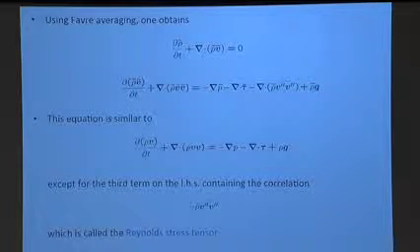The mathematical form of these is exactly the same, which is why, Reynolds, not sure if he called it the Reynolds stress tensor, but this is why we say it must have then the same effect somehow in the fluid as the viscous stress tensor. Okay? So we call this a Reynolds stress tensor, and we know this is the transport. How do you know this is not a production of momentum or consumption of momentum? How do you know this is a transport term?